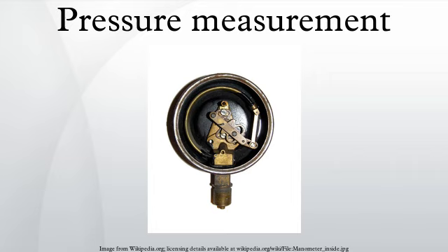Since dynamic pressure is referenced to static pressure, it is neither gauge nor absolute. It is a differential pressure. While static gauge pressure is of primary importance to determining net loads on pipe walls, dynamic pressure is used to measure flow rates and air speed. Dynamic pressure can be measured by taking the differential pressure between instruments parallel and perpendicular to the flow. Pitot-static tubes, for example, perform this measurement on airplanes to determine airspeed.